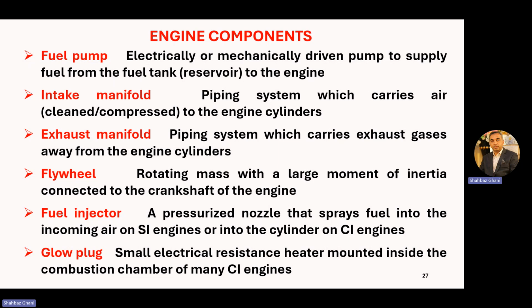This glow plug is different than a spark plug. A glow plug is basically a small electrical resistance heater mounted inside the combustion chamber of many CI engines. Before starting a CI engine, we normally use a terminology: let's start the heater. Basically, that heater is you switching on your glow plug. It heats up the surrounding air to increase its temperature for easy combustion.